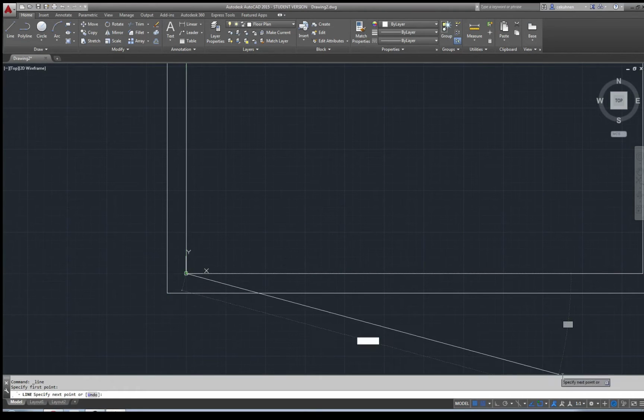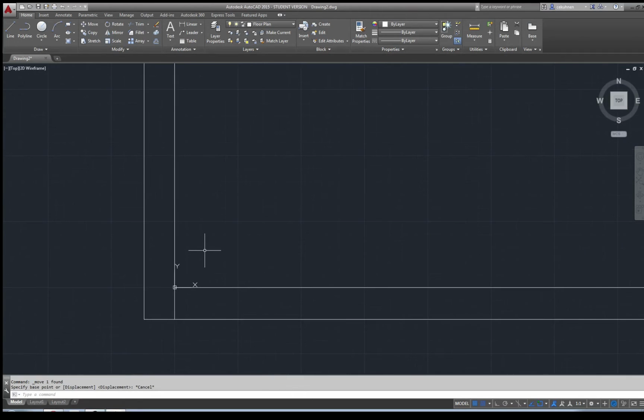and I would, for example, like to have intersection turned on. And you see where this X is, there it intersects, click and enter. There's now my line. This line, for example, I can move. I, for example, go to move, click this line, spacebar, click the reference point from where I would like to move from, click my mouse to the right, and for example then type in 13 inches.